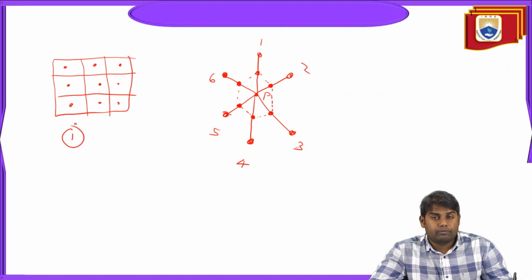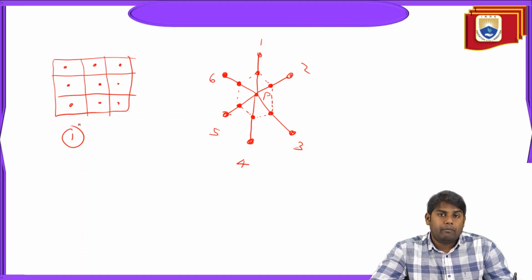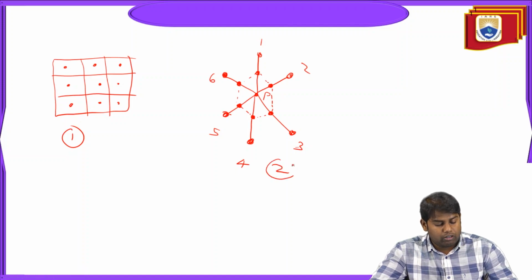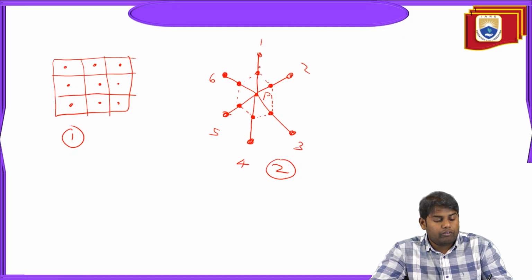So first approach is where we define the control volume and the cells. Then we will locate the centroids. And the second approach is we will first draw the nodes. So for the corresponding neighbor nodes, at the midsection of these neighboring nodes, we will mark the points and we will add the locus of all those midsections. Then we will frame, or we will get, a face. Okay. So this is another type of approach. In general, people perform the first approach compared to the second approach.